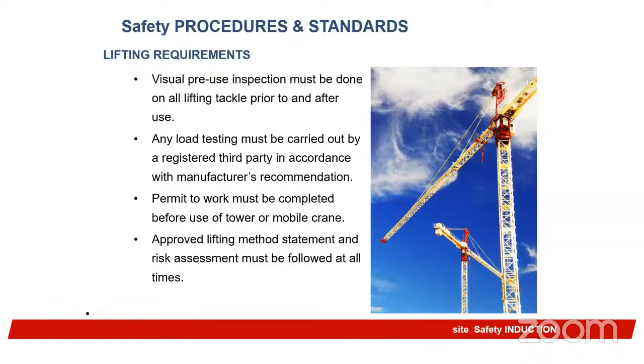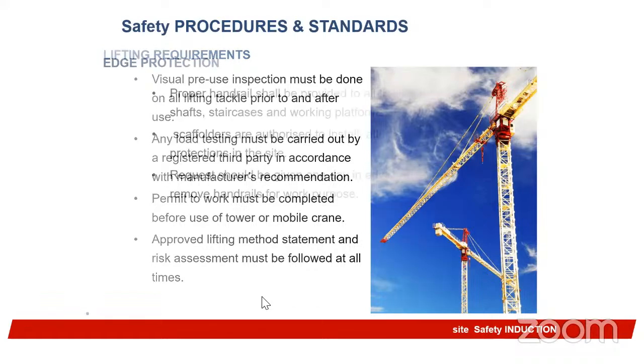Visual pre-use inspection must be done on all lifting tackle prior to and after use. Lifting shackles, all the equipment we want to use for the lifting, there must be proper pre-use inspection, a visual one, just look at it around. Any load testing must be carried out by a registered third-party person. Permit to work must be completed before use of tower or mobile crane. Approved lifting method statement and risk assessments must be followed at all times. This we have repeated so many times here.